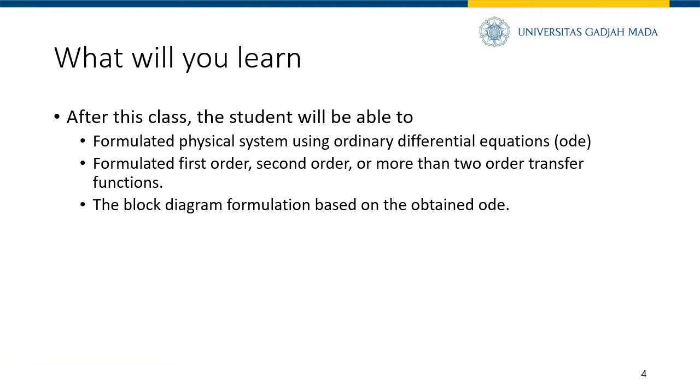and then after this class you can formulate a physical system using ordinary differential equations, and also formulate first order, second order, or more than second order transfer functions. And then the third one, you can make a block diagram based on the obtained ordinary differential equations.